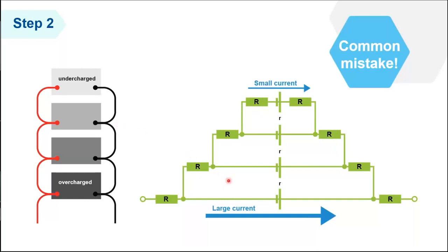And what is the drawback of this? Each set of leads has its own resistance and is additive. And the top battery will provide much less current than the bottom battery. And what happens if the battery bank is being charged? The bottom battery gets charged with a higher current because it sees less resistance in its path to the batteries. And the top battery gets charged with a much lower voltage than the bottom battery because there is a voltage loss until the voltage reaches the higher battery. And the result is that the bottom battery is working harder, discharging harder, and it will fail very soon.